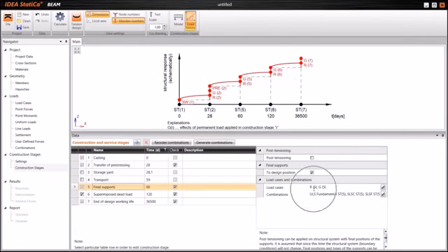You can see here that the load cases are R5 or G5, and also this G5, which was this additional superimposed dead load. So in these load cases, we store the increments, and if you sum all these load cases, you get the total value, which is the result of the combination, and it shows you the total structural response of the structure on loads applied in individual construction stages. This is the principle.